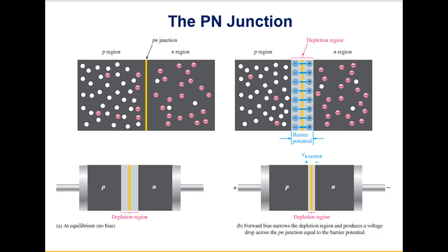When a single piece of silicon is doped with P-type impurity at one end and N-type at the other end, a P-N junction is formed where the two oppositely charged sides meet. Around that junction, a depletion layer is formed. What that means is that at the instant of P-N junction formation, the free electrons in the negative region, or N region, near the junction begin to diffuse across the junction into the positive region, or P region, where they combine with the holes in the positive region.